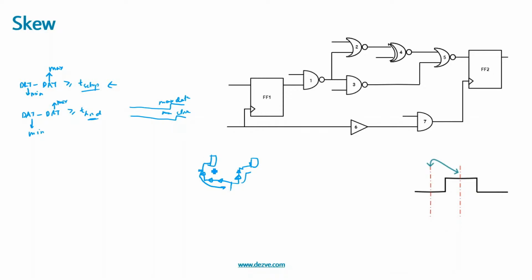Now if we add the skew for setup analysis, the clock would get delayed further and would get more margin, correct? But the skew can be any value, correct? The skew here is at the synthesis stage, not post placement and post CTS. Post CTS actual skew will be computed, correct?